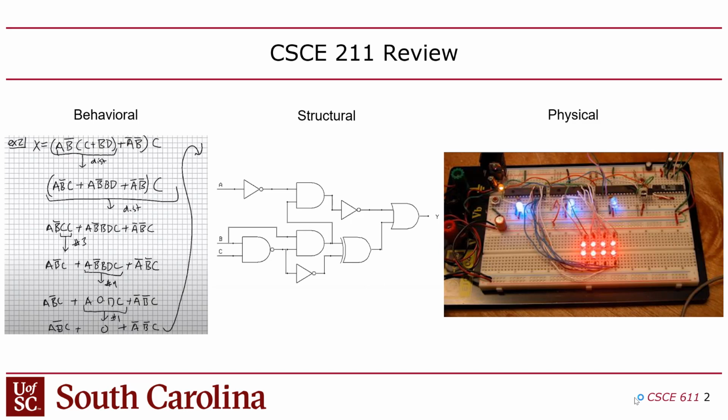So you're basically selecting devices from a repertoire. Typically that repertoire is comprised of devices that are pre-designed, but that's assuming that you're using bottom-up design, where you're designing things and then using those things, as opposed to top-down, which is where you would put things in a schematic that aren't designed yet, and you'll worry about designing them later.